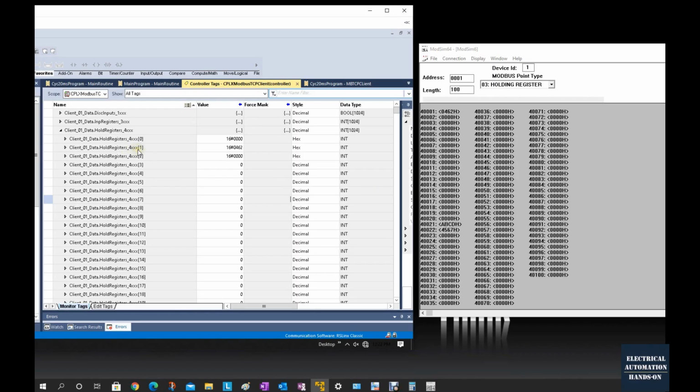Here in the PLC side, that is the 40,000 address. Now we are reading the data from this server to here, and this Modbus address, that is 40,001, and we receive the data as this 1, this index here. So if we set a new value here, double click and write 7788, we can see 7788 we received correctly.